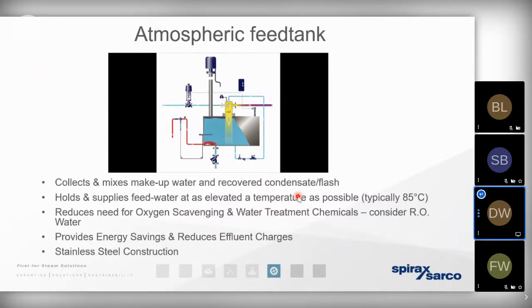Now, we've already mentioned that condensate, that hot water, doesn't have any value at the process because it's got nowhere near enough heat energy to keep the heat exchanger at the operational conditions, but it's still hot water. So if we can recover that hot water back to the boiler house, we can keep it in storage in the hot well until such a time that the boiler requires hot water in order to keep up with and match the required amount of steam for the process.